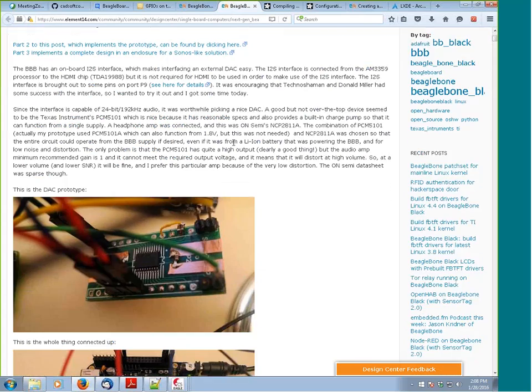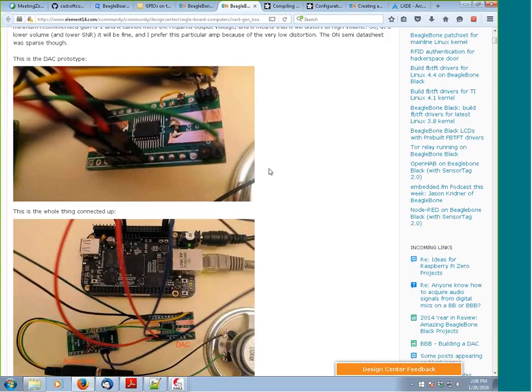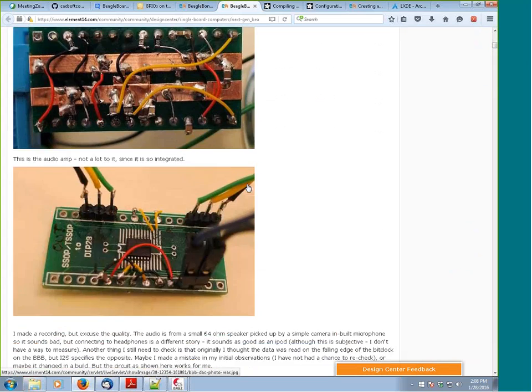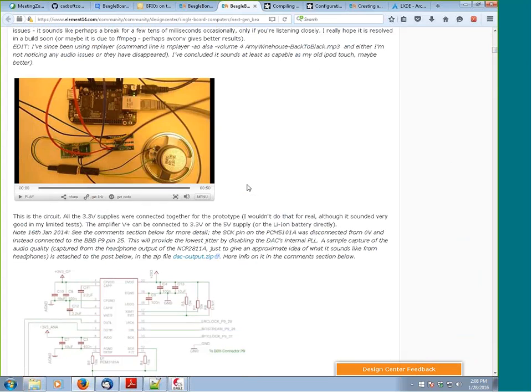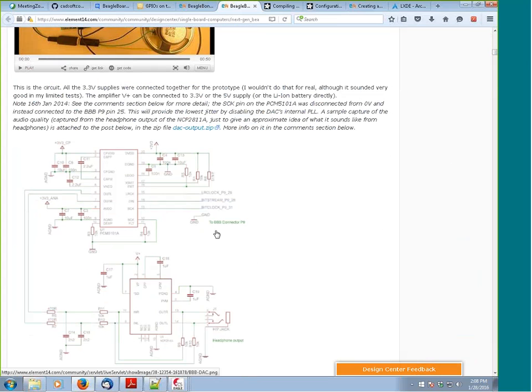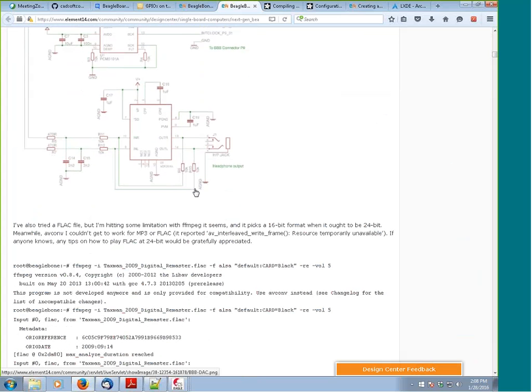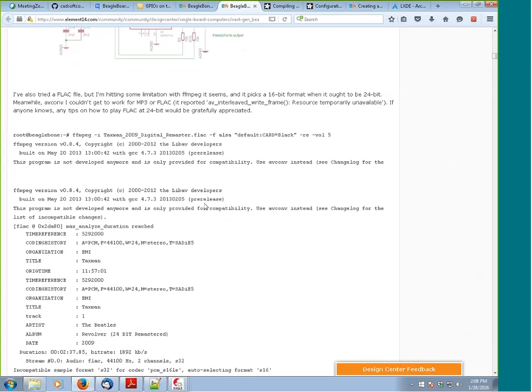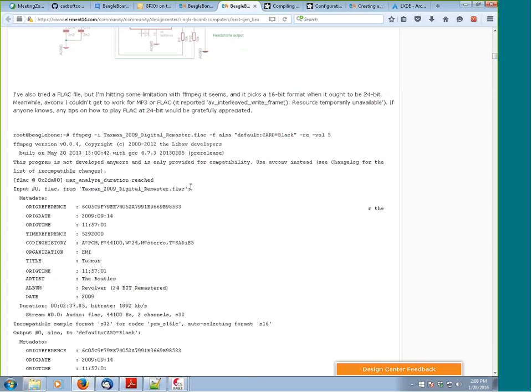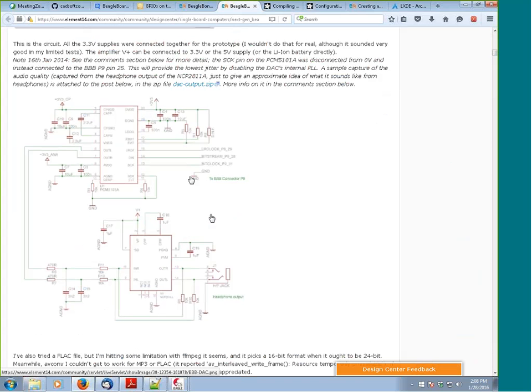Okay, which is here. He basically put up a series of blog posts using the PCM5102 audio DAC, which is exactly the part that I used for my design. And even though he made the schematic available, he didn't make the layout available. His board also had a lot of other stuff that I didn't need for my purposes, so I ended up stripping a lot of the design away. So in essence, I basically redrew everything from scratch and laid out the board from scratch. So even though the original design intent is his, the rest of the board is basically mine.